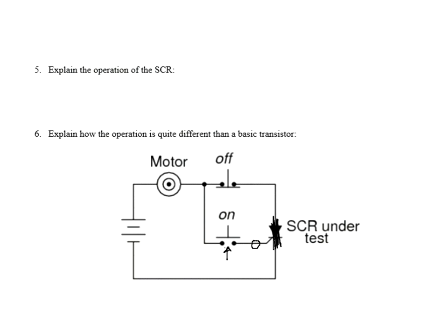But an SCR loses control. The gate loses control once it's on. Now, the only way I can shut that SCR off is with this switch to interrupt the current in the anode or the cathode. When I press that button, and this button is open down here on the bottom, right here, as long as that button stays open, when I press that button and it opens the switch right here, that resets the SCR and it goes back into its off state. Then it shuts off. And it won't turn back on again until that switch on the gate is turned on.